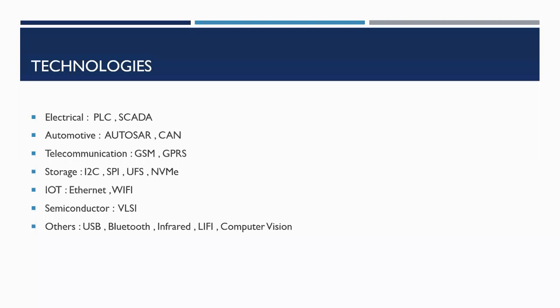Now, when somebody is interested in the automotive domain, they can be very good in understanding the CAN communication protocol and the AUTOSAR concepts. Here, AUTOSAR is not a separate tool; it is a standard. In this standard, companies follow certain layers of developing the software. Those layers need to be understood, and the engineers have a role to do in those layers only. There is the MCAL layer, the microcontroller layer.